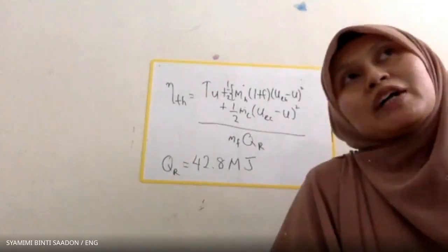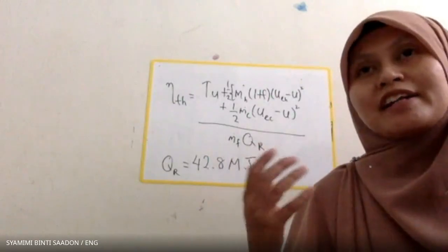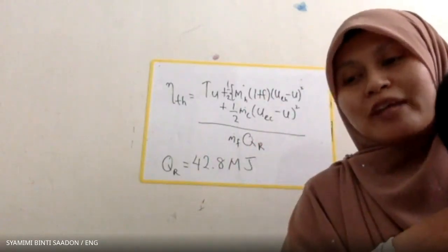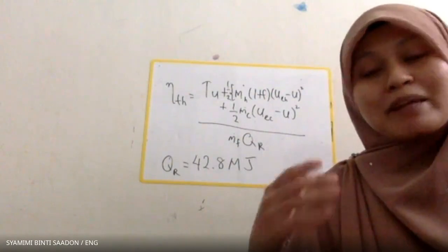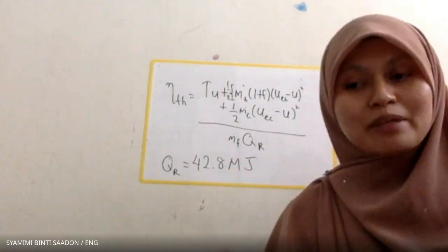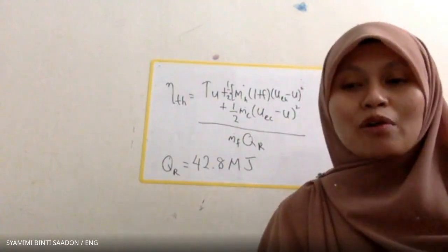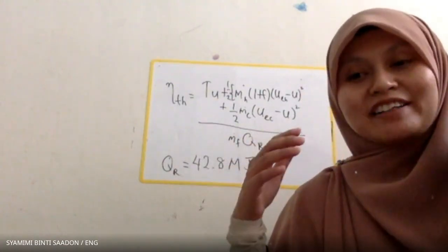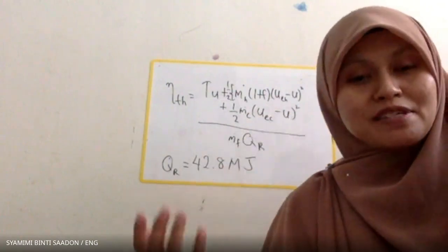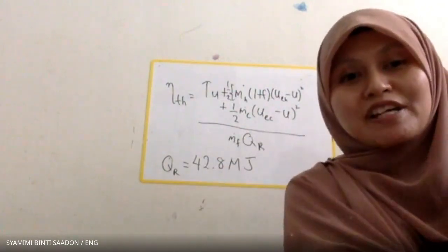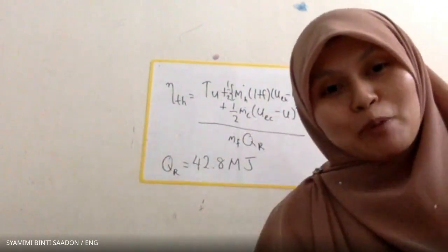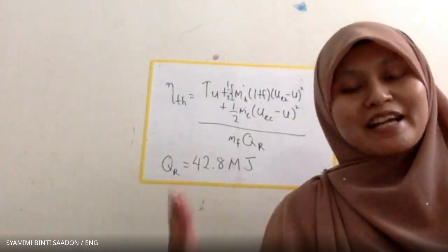Because normally if you want to design or modify an engine to get a better engine with better fuel consumption, better fuel saving, obviously you have to evaluate the TSFC of the conventional engine and compare it with the new design engine that you are going to propose. We normally compare the TSFC.